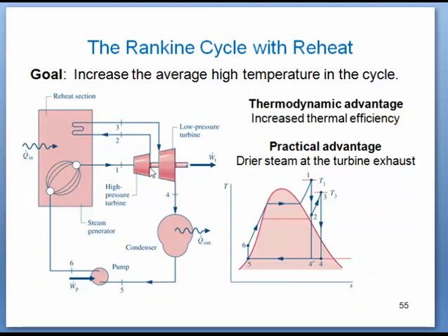The steam enters the HP turbine, and after expansion it passes through the reheater. Again this reheated steam expands in the low pressure turbine or intermediate pressure turbine, depending upon the case. So the benefit we are going to get here is an improvement in cycle efficiency, because overall we are getting more net work output from the turbine.